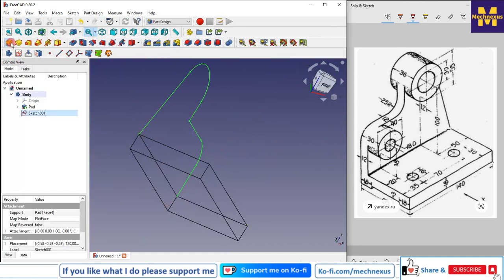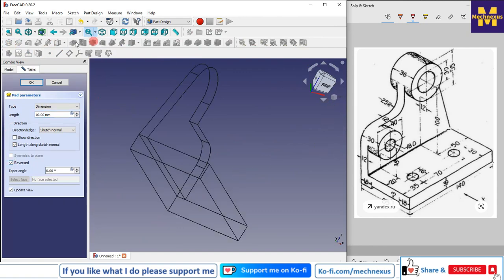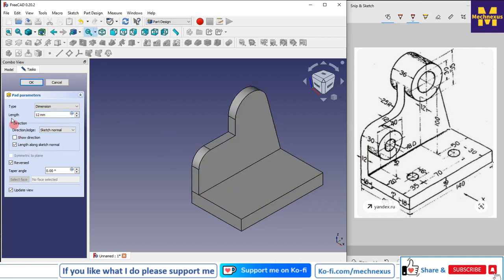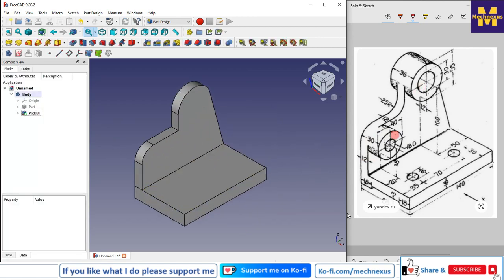Now I will click on the pad and I will say reverse, and from here I will switch to the flat lines, and from here isometric. So this is the 12 mm, so I will give it 12 mm and I will say OK. So this is how we have made this overall profile. And now we will make the cut here.